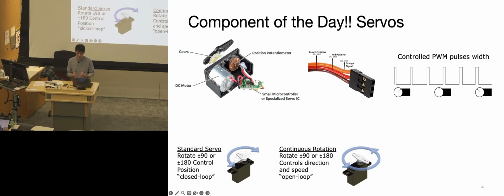It's a rotary, or sometimes linear, but usually rotary actuator that allows for precise control of the position and sometimes speed and acceleration. You will see in the top left figure here, you usually have a DC motor inside the little package, and then a potentiometer that acts as a built-in feedback system that knows the current orientation based on the current reading of the potentiometer. So it will keep the angle at a particular position, even if you overshoot or turn it around, it can likely adjust it back.